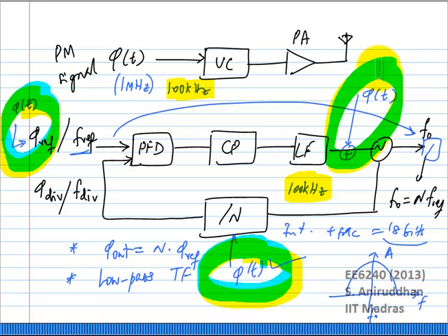Not much. Okay, because you anyway had your fractional divider and you had static data going in. Now you have maybe a very low frequency 1 megahertz data going in. Getting your fractional path to work at 1 megahertz is very straightforward. No problem with that. Same thing goes with this path also. Same thing for the reference path also. 1 megahertz is very low frequency compared with the signal frequencies we are talking about. And same thing with this side also. Okay. So really the extra circuitry you are talking about is not very complex.